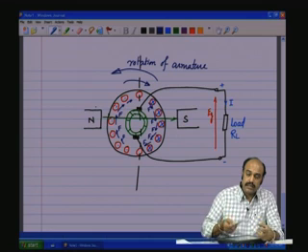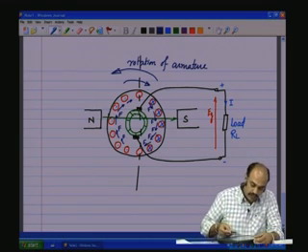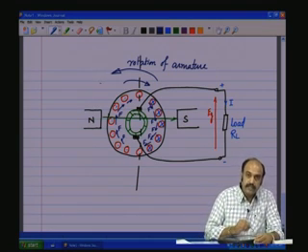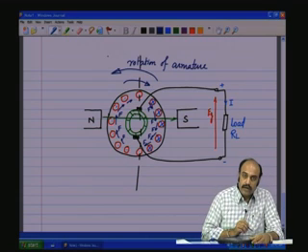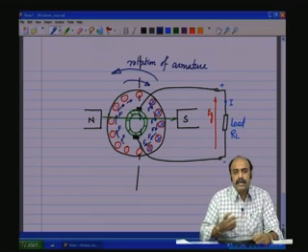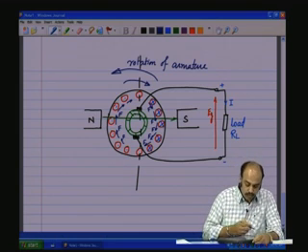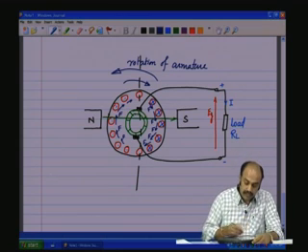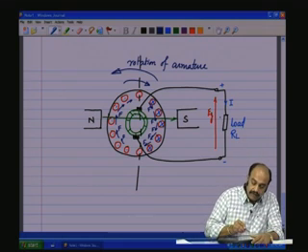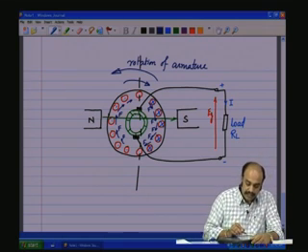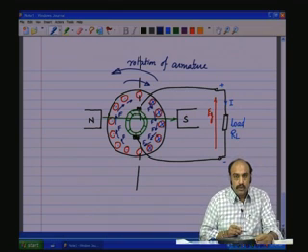So, an extra power has to be generated by the prime mover, which will try to force against this clockwise loading effect torque, such that the armature continues to rotate in the same speed. So, thereby it draws more energy from the prime mover and dumps it to the electrical side. This is the energy conversion process on loading. Okay. So, this is how any load gets reflected onto the mechanical shaft and thereby acts as a load on the prime mover.